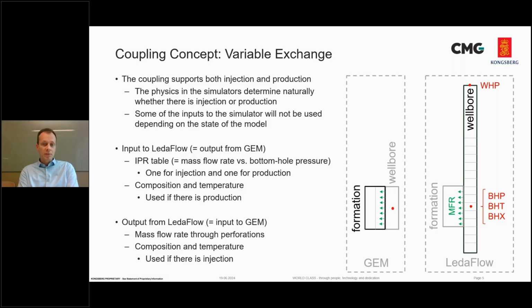And then the LedaFlow domain, it doesn't really simulate the formation, that is handled in terms of an IPR. But LedaFlow has a very detailed discretization of the wellbore, where we define the wellhead pressure at the top and the bottom hole pressure, temperature, and composition at the bottom. And so those define the different variables.